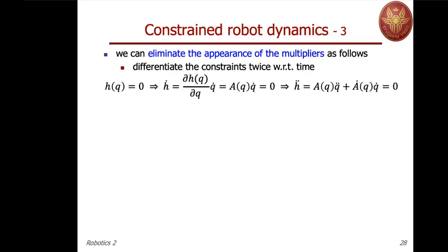Now, this is in fact a matrix, a Jacobian, but it's not something related strictly or only to the task function associated to the robot, in particular to the end effector Jacobian, if we are constraining the end effector, but contains also the information about the type of constraint. So it's a specific Jacobian which relates the task variable of the robot with the geometric information on the constraint imposed on it. And we will see this very clearly in the following assumption.